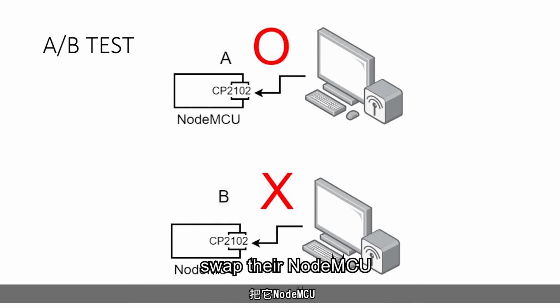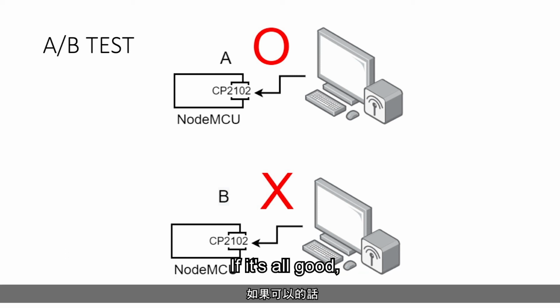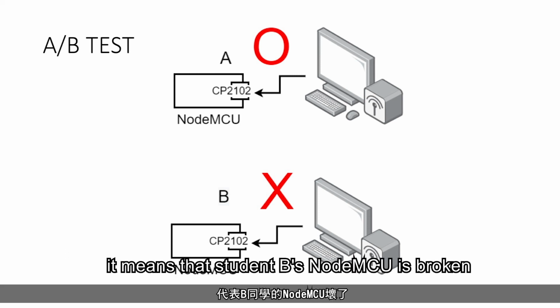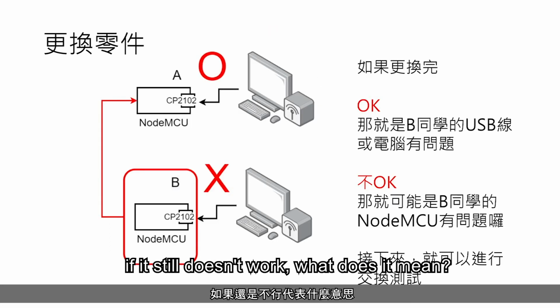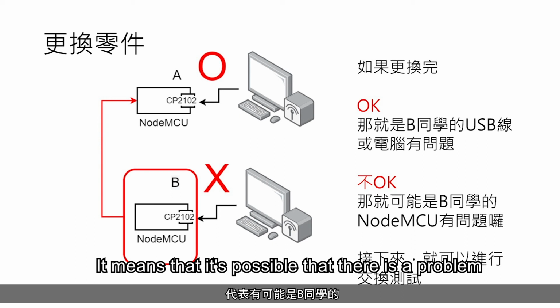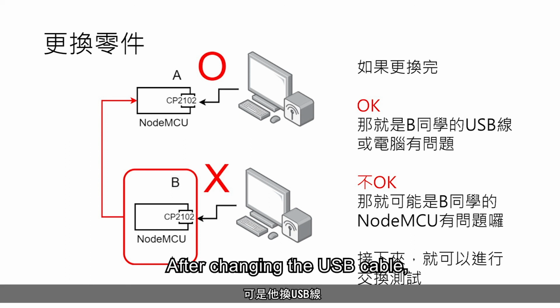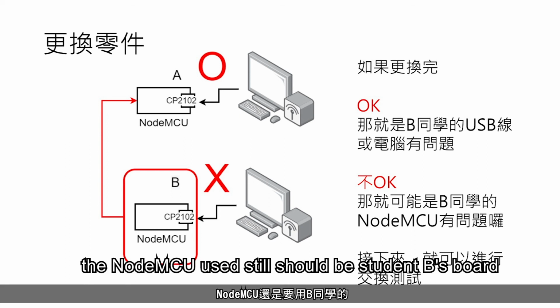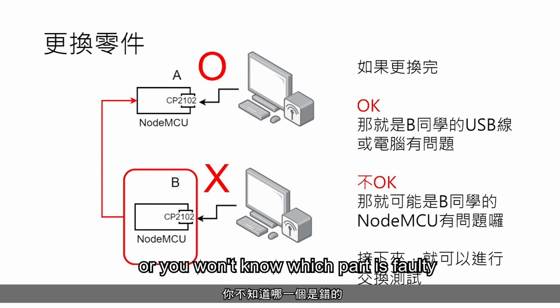Student B and A swap their Node MCU, and perform upload and download to see if student A is all good. If it's all good, it means that student B's Node MCU is broken. If it still doesn't work, what does it mean? It means that it's possible that there is a problem with student B's USB cable or computer. Then we change the USB cable. After changing the USB cable, the Node MCU used should still be student B's board. You can't change 2 parts at a time or you won't know which part is faulty.